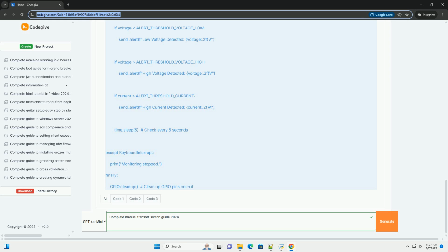5. Power restored. When utility power returns, switch the transfer switch back to the utility position before turning off the generator. This prevents a surge when the utility power comes back on. 6. Turn off the generator. Turn off the generator and let it cool down before storing it. 7. Turn on main breaker. Turn the main breaker back on. 8. Troubleshooting.